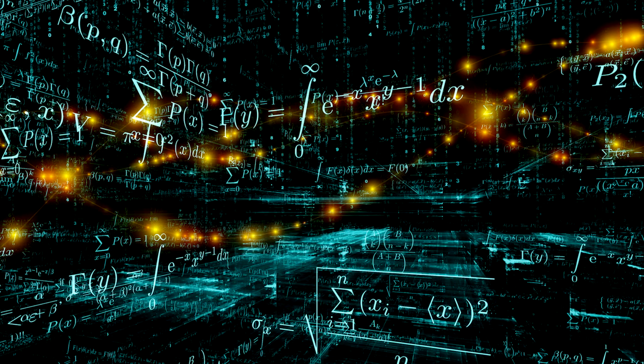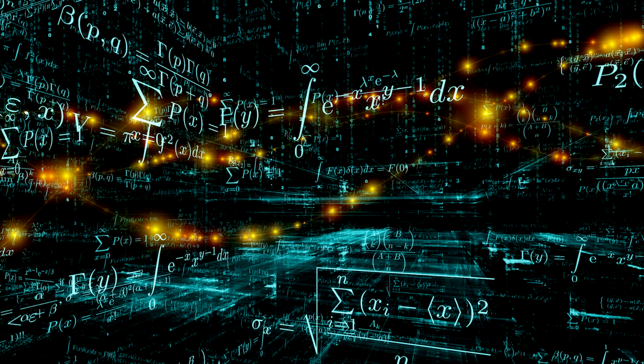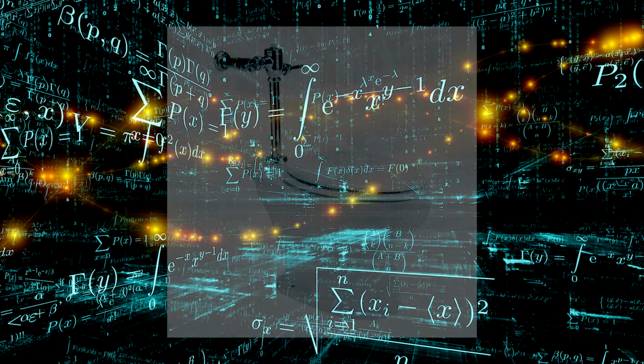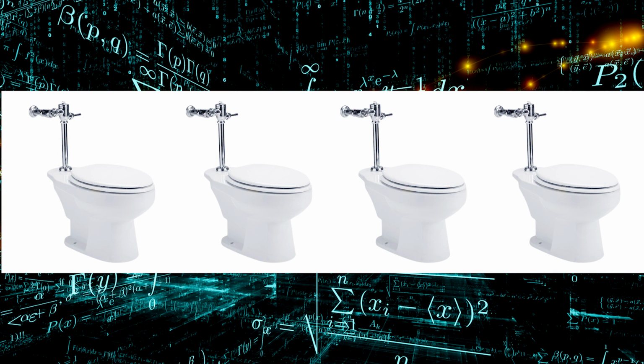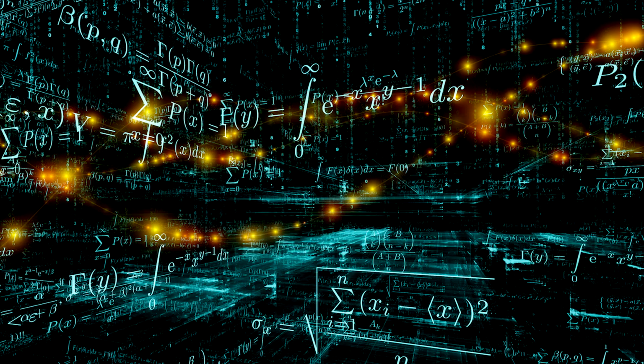Now you may be asking the question, why are these fixture unit values so high for direct flush valves? And why, if you only have 1 of them, are they just through the roof high? Well, that comes down to just considering this scenario. You have a commercial building with only one water closet. That water closet is going to get a great deal of use. But if you had a bank of, say, 4 water closets in the same bathroom, people are going to be able to pick and choose, and you're less likely to have all the water closets running at the same time, maybe 1 or 2. So all 4 of them get a little bit less use. So just think about it that way.